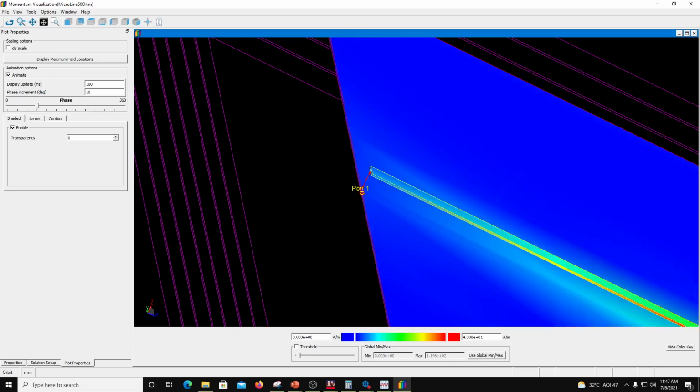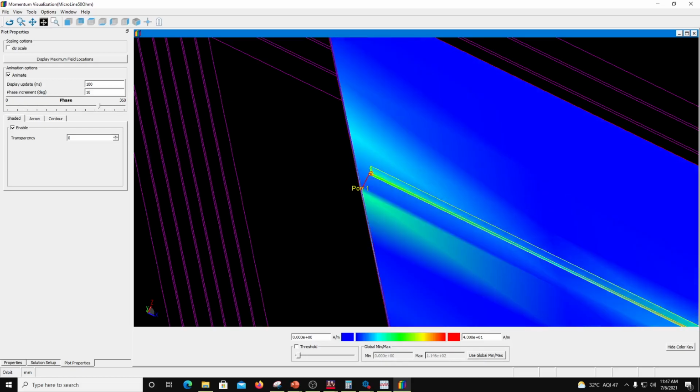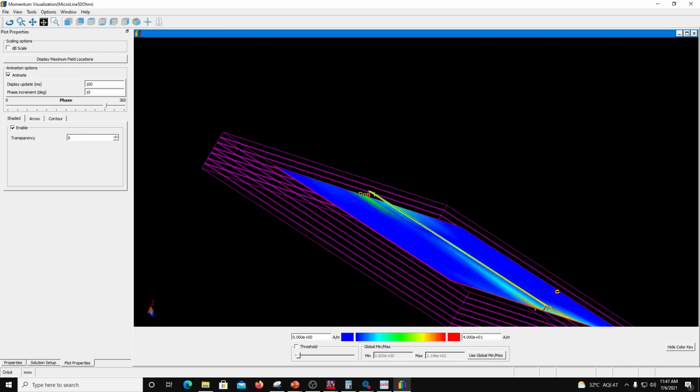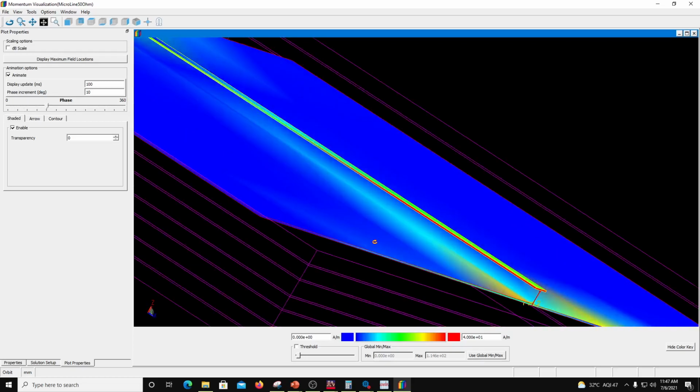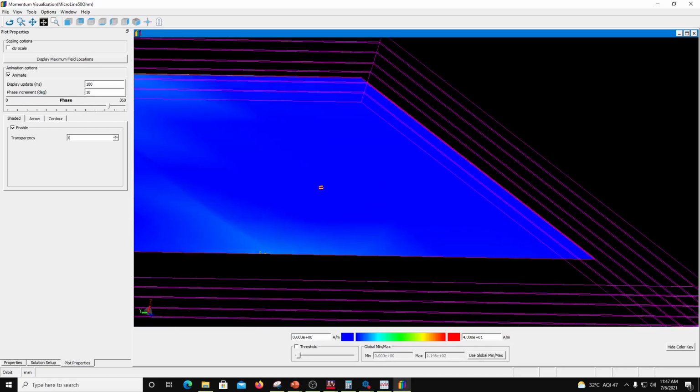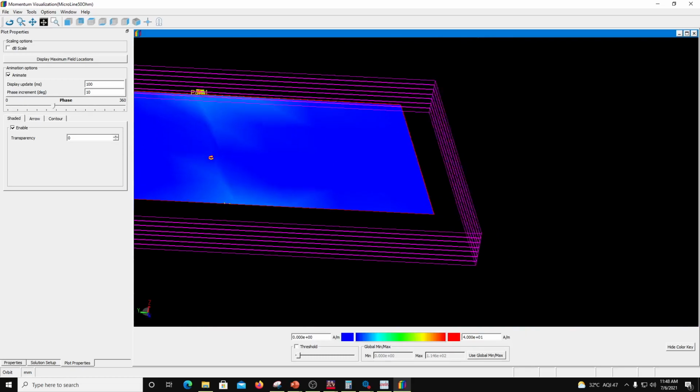And whatever is your impedance, the impedance is relative to the local ground. So whatever is the ground voltage here, the voltage of the signal with respect to that ground voltage divided by the current will give you the impedance here. So the impedance of the line depends on the local ground. So you see here port 2 has its own local ground and port 1 has its own local ground, and this is not 0 volts because the ground plane has got currents.